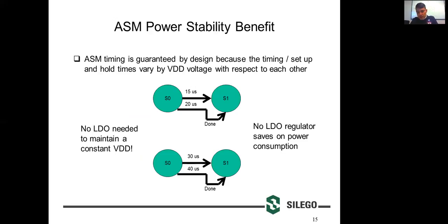You could hook these up to a lithium-ion battery directly that charges up at 4.3 volts and discharges all the way down to 2.3 volts, and without regulating anything in our chip, our asynchronous state machine will not crash, won't have any kind of timing problems, will be completely stable that entire way, and you could even jerk that power supply up and down. It's an incredibly robust piece of circuitry, and that is just the nature and architecture of the asynchronous state machine.